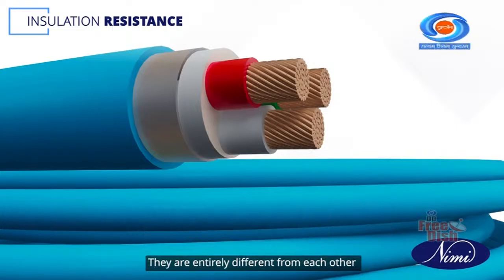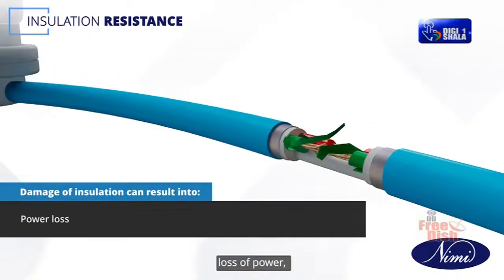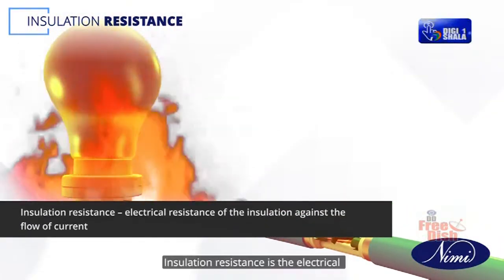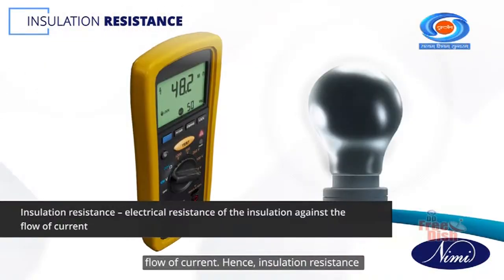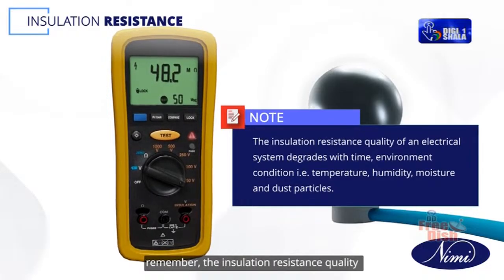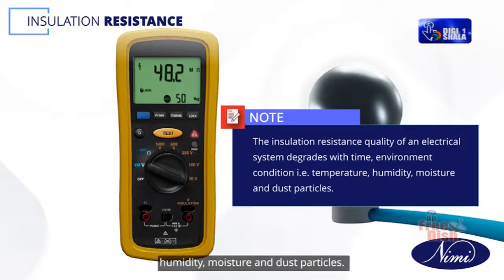Two fundamental properties of insulation materials are insulation resistance and dielectric strength. They are entirely different from each other and measured in different ways. Damage of insulation can result in loss of power, overheating of equipment, and even fires. Insulation resistance is the electrical resistance of the insulation against the flow of current. Hence, insulation resistance is to be maintained to ensure safety. Please remember, the insulation resistance quality of an electrical system degrades with time and environmental conditions, that is, temperature, humidity, moisture, and dust particles.